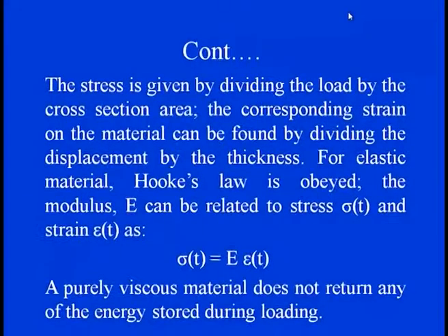So when this displacement is like that, the stress is nothing but the load per unit cross sectional area, and the corresponding strain is the displacement divided by the thickness. Since it is elastic behavior in these materials, Hooke's law is very well valid.